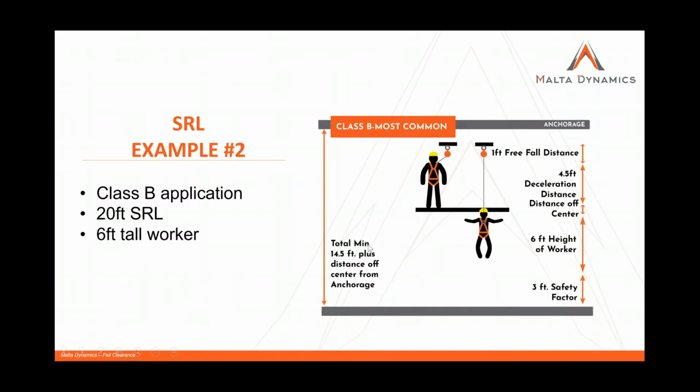Does everyone understand that? That's a calculation you have to take into consideration when you're analyzing the hazards and then figuring out where your people are going to be working and how far away from the anchor point they're going to be able to walk, which should never be more than a 30-degree cone.